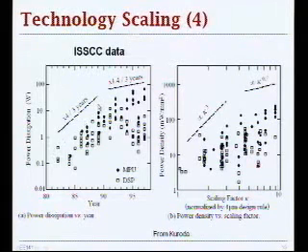You didn't scale your voltage, you just scaled your transistor dimensions, which results in much higher power than if you scale the voltages as well. In the 90s, people started doing voltage scaling, and we will discuss the scaling scenarios in a minute. The leveling off of the power consumption was caused by simultaneous scaling of both your dimensions and your voltages.